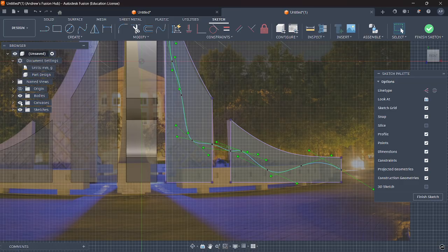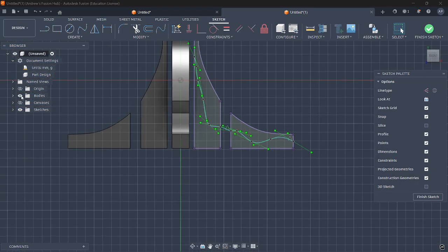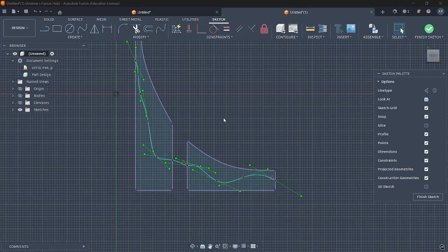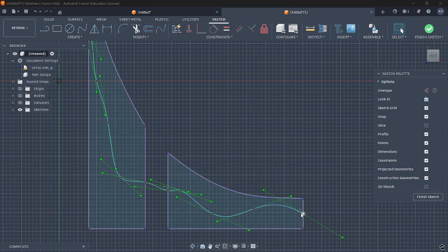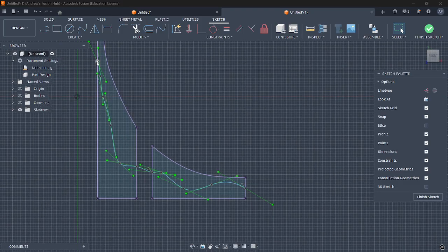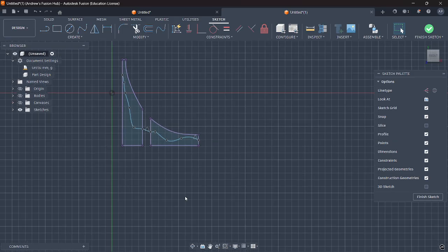So if I hide the canvas, even the bodies, you can see what I did here, right? I projected these faces and then I drew on it. I drew this detail line, but you can see because we have these endpoints here, it splits the whole original body into 4 different pieces. So we can select these things and manipulate them for extrusions or whatever we want.